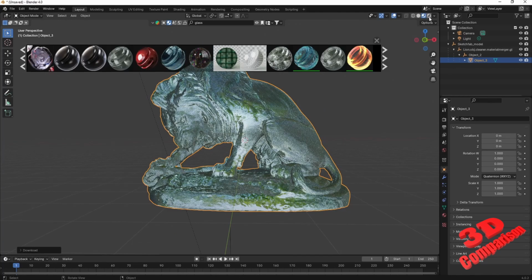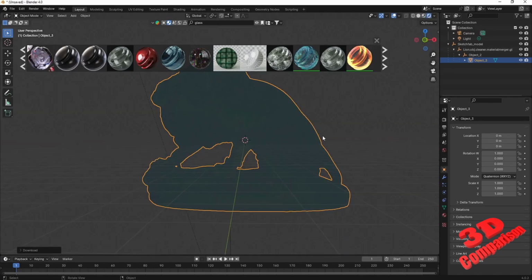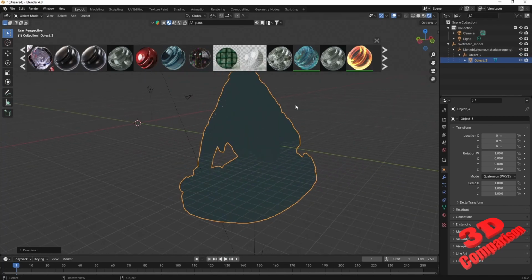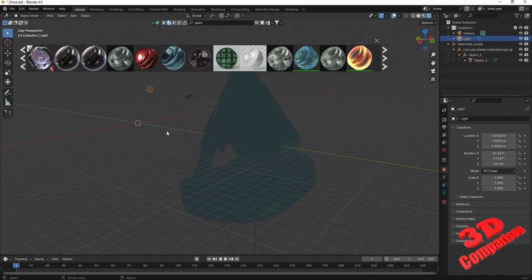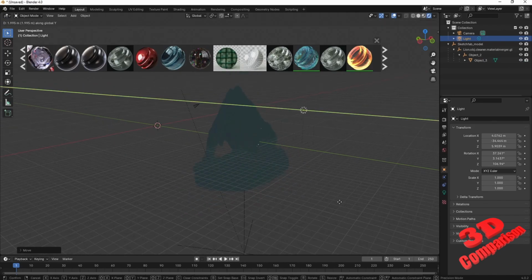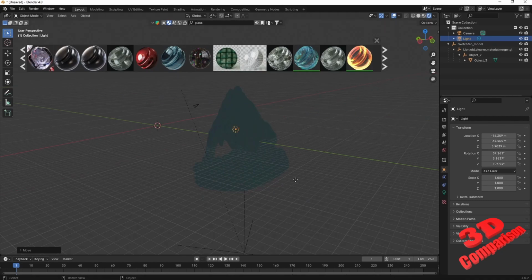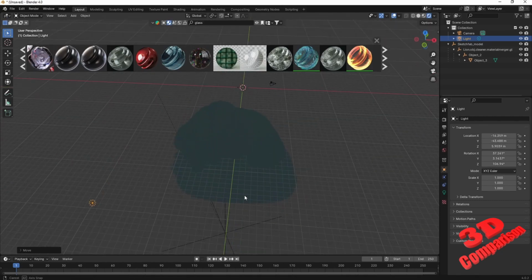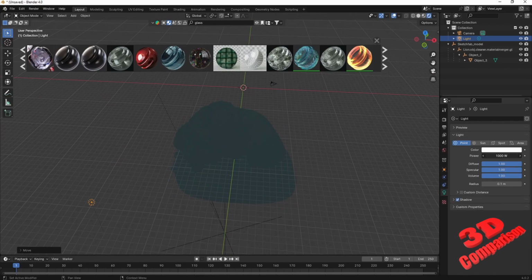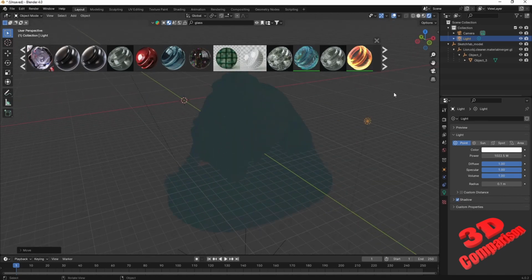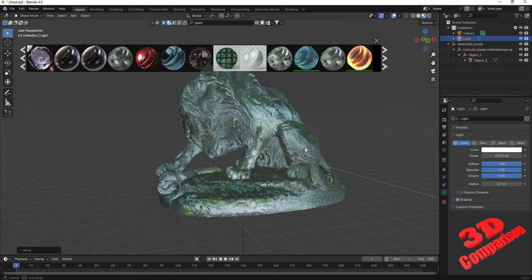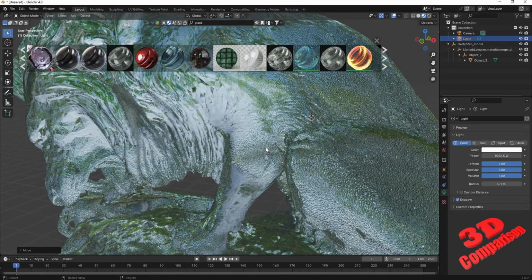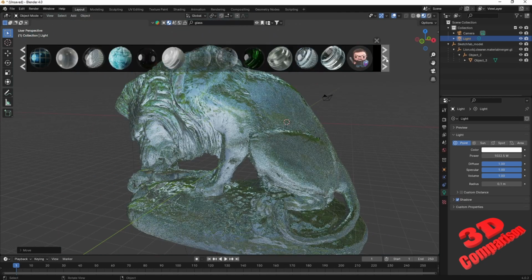We can later add background light, because currently within the scene we only have one light source over here. If I move this a little bit closer to our mesh, we're gonna see how that will start to influence the model. So this will be that light over here. We can go to the light properties, and we can also increase the power for that light. But for real-time visualization, not for final renderings, we can just go over here on Visualize with Material, and we're gonna see how those details will look.